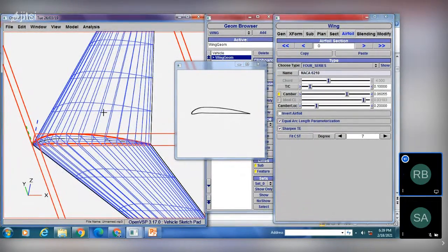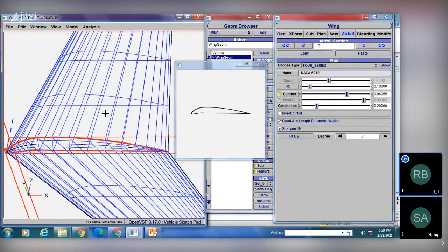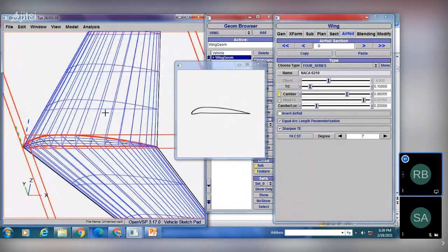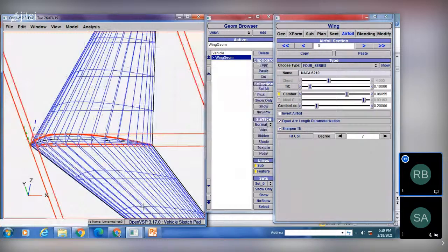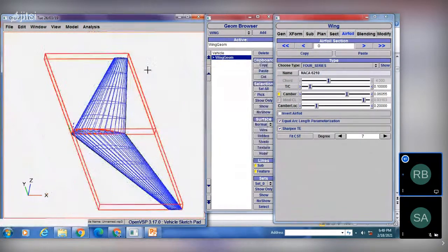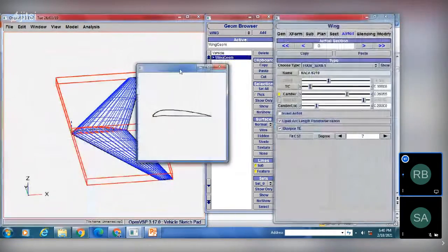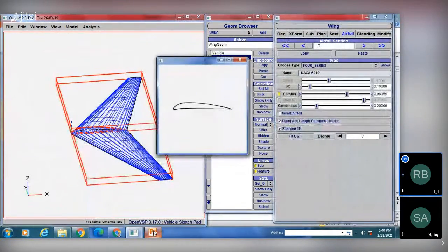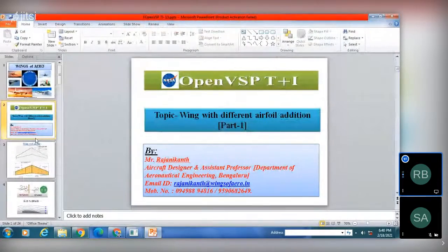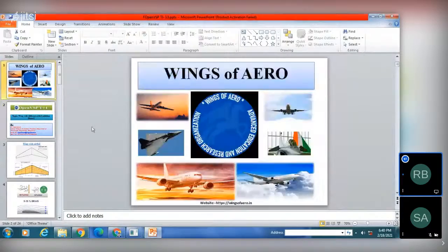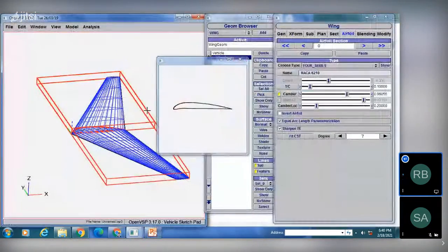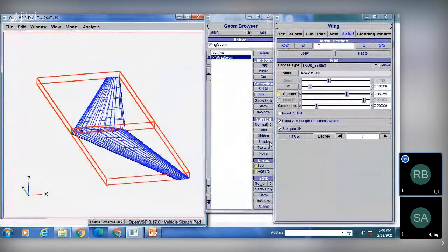Okay, so like this, we can design the aerofoil, which means we can design our complete wing by placing this kind of aerofoils as per your requirement, like 4 series, 5 series and other series aerofoils. And you can increase your lift coefficient, meaning the overall lift coefficient CL.